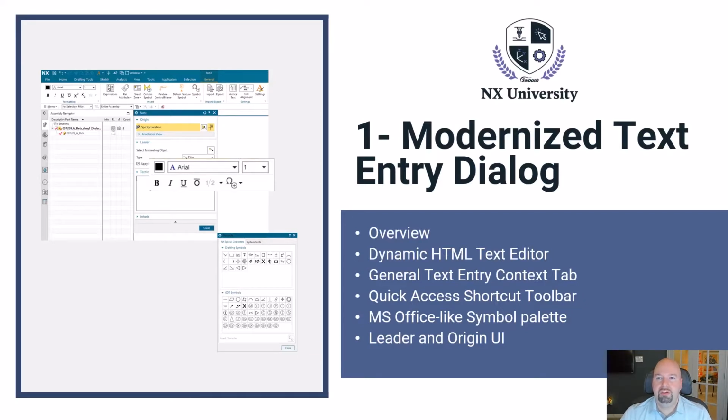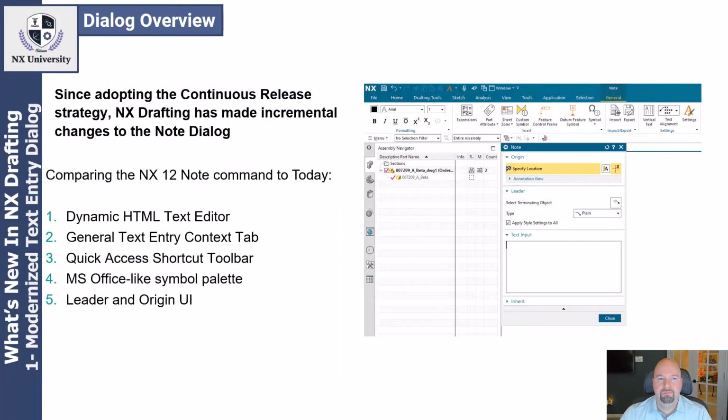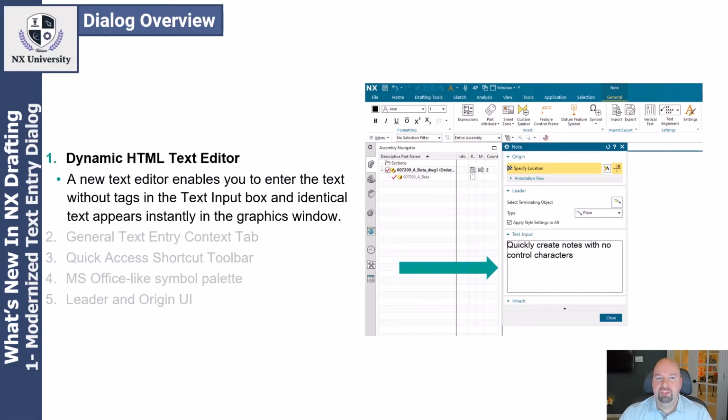Jumping into the first topic here, modernized text entry dialog. With the new modernized text entry dialog, which is the note dialog we're referring to here, since adopting the continuous release strategy, NX Drafting has made incremental changes to the note dialog. Comparing the NX12 note command to today, we now have a dynamic HTML text editor inside that note dialog. A new text editor will enable you to enter the text without tags in the text input dialog, and it will be identical to the text that appears instantly inside the graphics window. So what you see is what you get here.